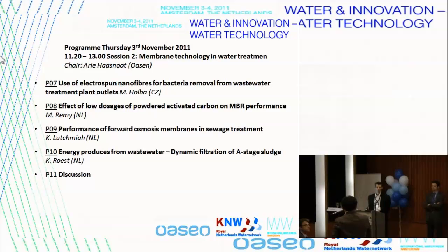Based on my experience, yes, it is less prone to membrane fouling. However, I'm not sure about energy saving with the current FO technology yet. Is magnesium chloride the best draw solution for your system, based on your presentation? And how are you going to separate your magnesium chloride from your water?